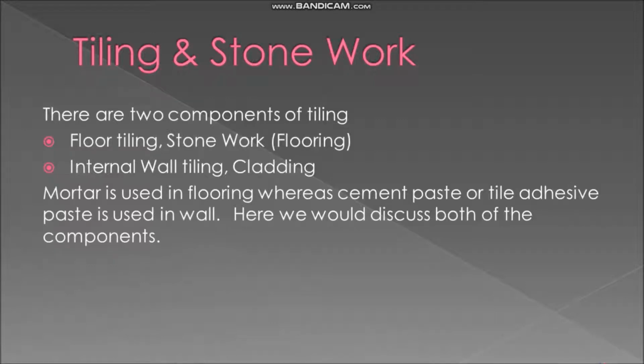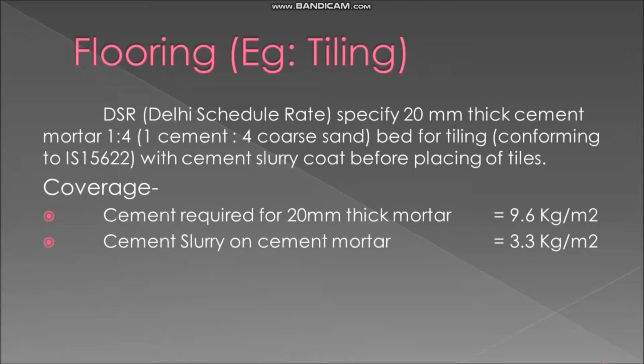Flooring. DSR (Daily Schedule Rate) specifies a 20 mm thick cement mortar bed, that is a 1:4 ratio of cement and coarse sand, and after that the cement slurry coat is required.